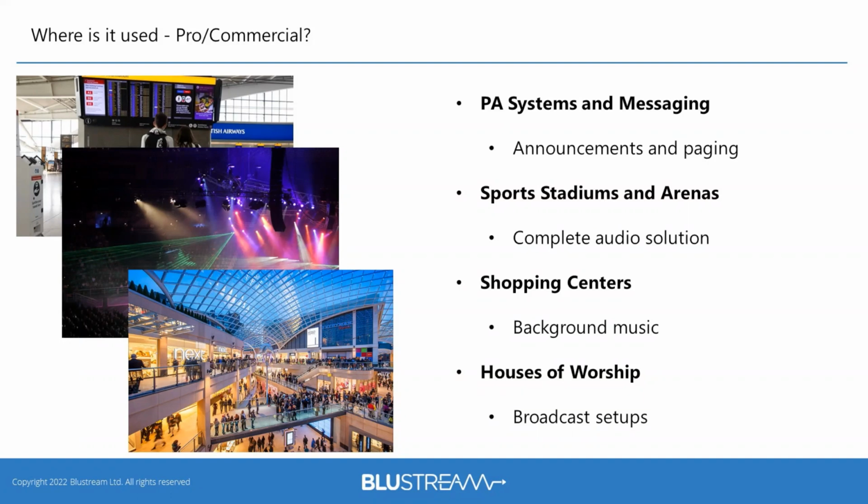We've even been part of yacht and marine transport projects where the number of cable runs needs to be limited, and by using only a single cable standard makes it conducive for use in those types of installations. By Dante's standard definition, you can host up to a 512 by 512 audio network on a 1 gigabit link at 48 kilohertz and 24-bit resolution. Now that's a lot of audio we can support on one cable by using Dante.